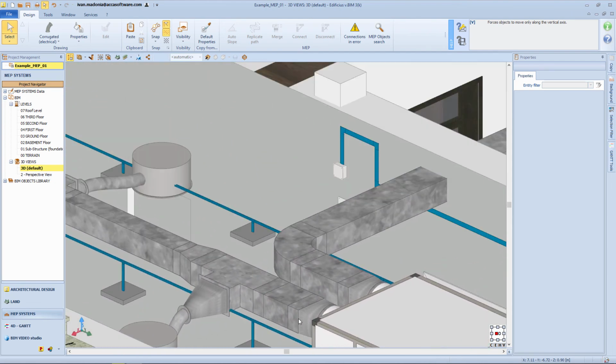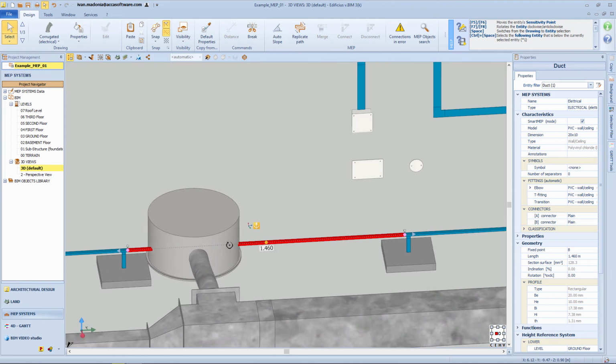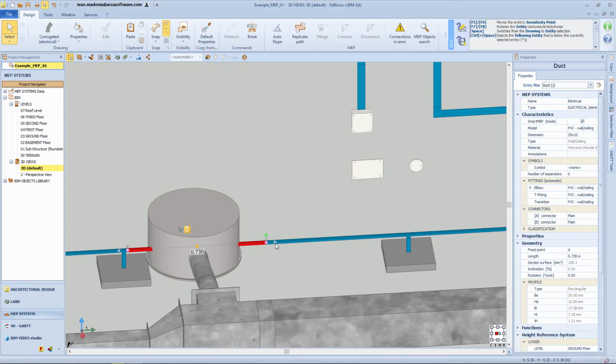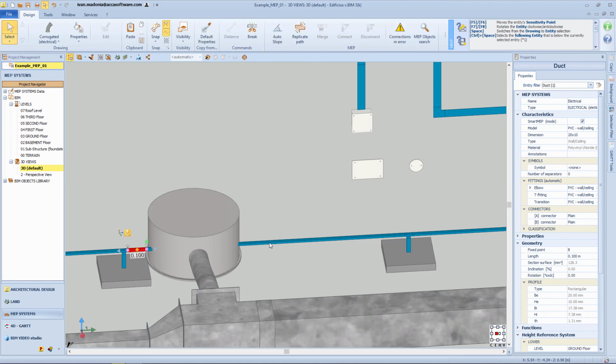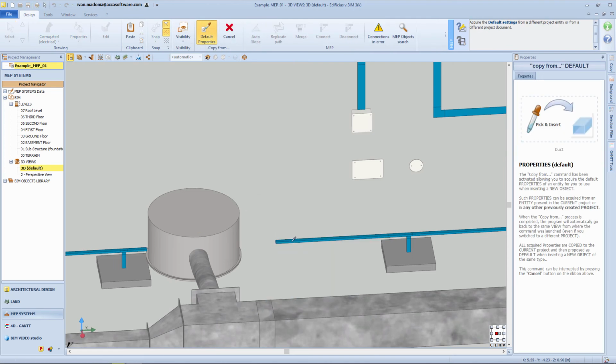You can of course also view the other systems that may be used in the project at any time, in order to check for any conflicts between the various entities and intervene to resolve them. For example, in this case, a section of the duct network interferes with a circular diffuser previously arranged within the ventilation system. This section of electrical connection is then appropriately remodeled.